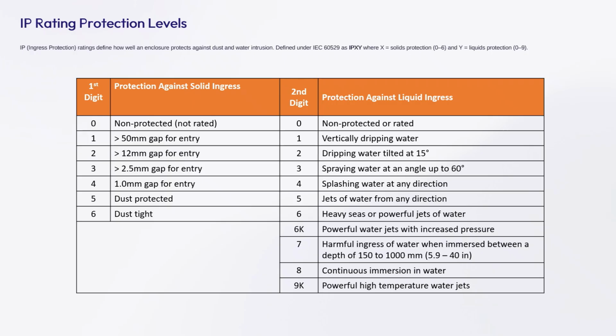IP54. Dust protected and resistant to splashing water. Common for indoor applications where there's light dust or moisture. IP65. Fully dust-tight and protected against water jets. This is suitable for outdoor installations.